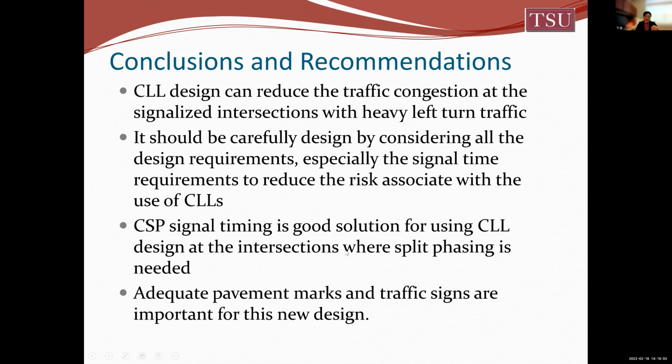The third one, I want to emphasize, the CSP signal timing strategy we propose is a good solution for using the CLL design at an intersection where we need to use split phasing. The last one, for this kind of new innovative design, we always need to provide enough pavement marks and traffic signs. We have to put lots of advance traffic signs to let people know what the design is and how they can safely go through the intersection. This is always very important for innovative intersection designs.